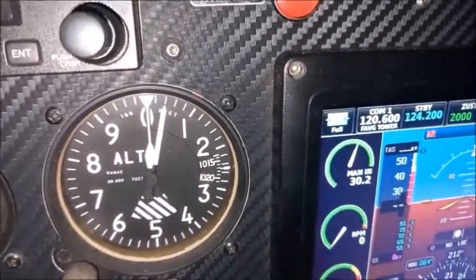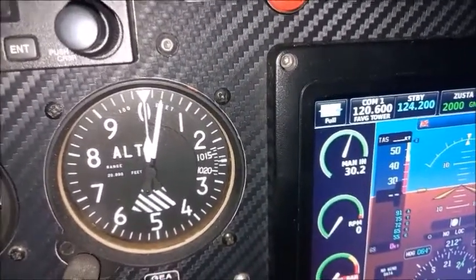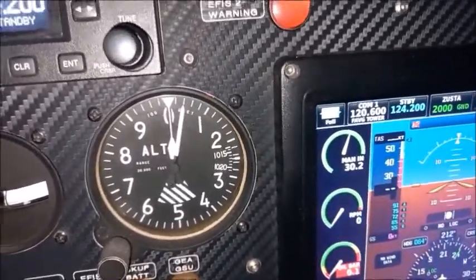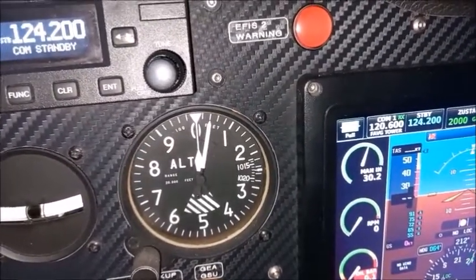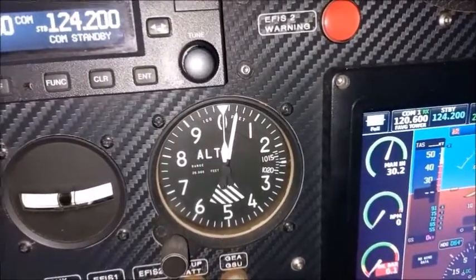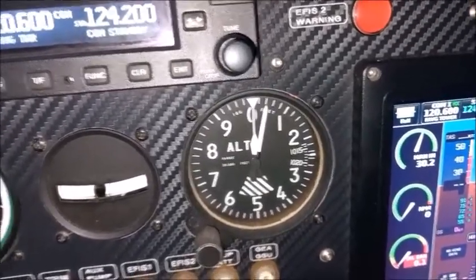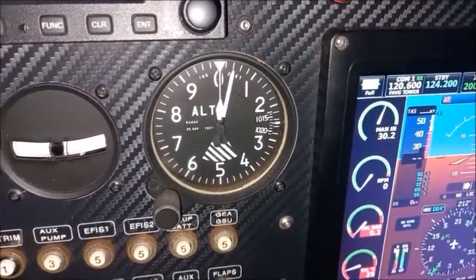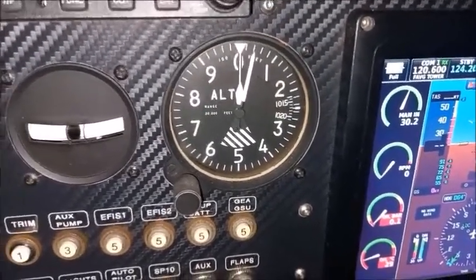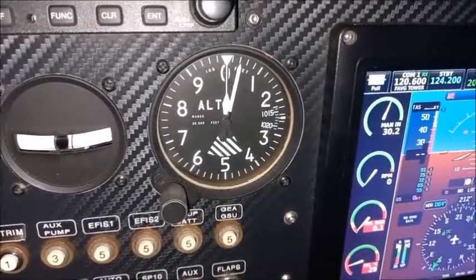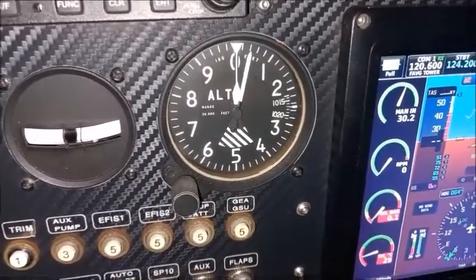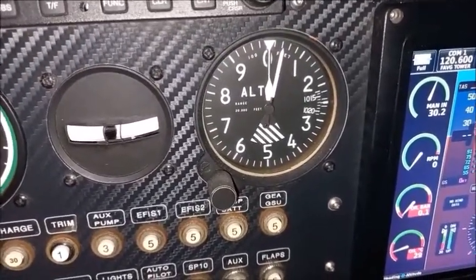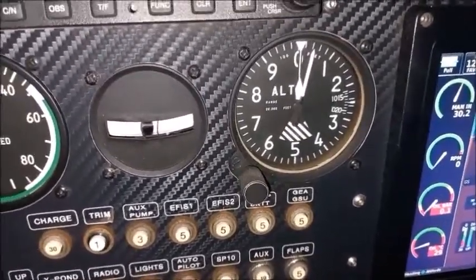So essentially what happens is that the altimeter uses a pressure sensor to determine how high the aircraft is above sea level. But the issue that we've got is that the sea level, or the initial height, can change. This is mainly because if, for example, a cold front is coming through, this cold front can cause a low pressure to come across the country, which is going to have an effect on the air pressure, and that could indicate to us that we might be at a higher altitude compared to what the aircraft actually is.